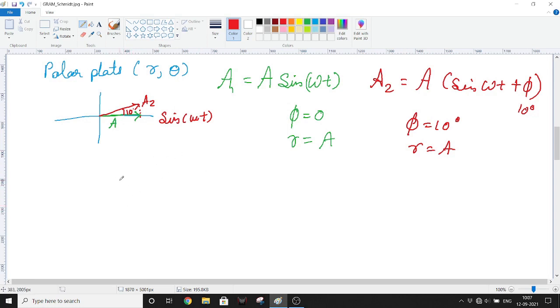So in this case, if I represent my ASK, consider the 4 ASK that we saw just a second before. What were our amplitudes? Our amplitudes were A1, A2, A3 and A4, represented with unit 0, unit 1, unit 2, unit 3. And now we shall represent these arrow marks instead of a complete vector with only one dot. A dot which is there at a distance a from the origin, that is O over here, and at an angle phi from the positive direction of x-axis.